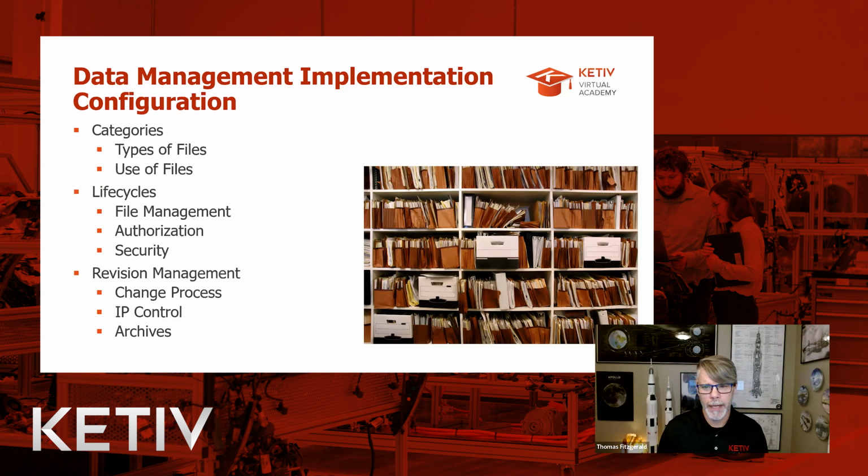Okay. When it comes to configuring our PDM specifically with Autodesk Vault, we want to take a really close look at these three items here: categories, life cycles, and revision management. Okay. So first, let's talk about categories. What are categories? Why should we be concerned about categorization?